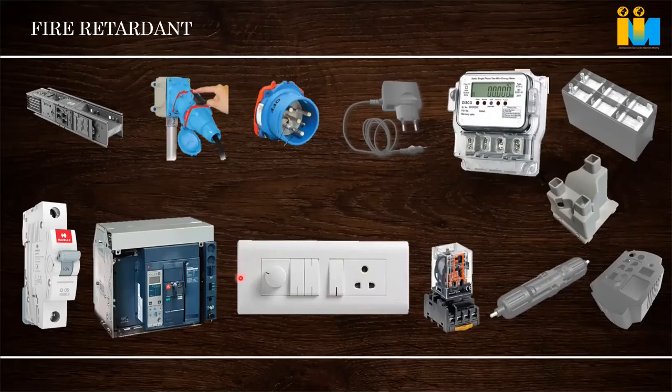And wherever there is no electrical conducting part, like a knob or something, they use V2, next-lower grade, or V2 or V1 grade. Okay, these are the metals selected. So at the bottom backside of a switch, wherever all the terminals are there, V0 grades or PBT fire retardant grade will be used. But for the front area, polycarbonate is used.